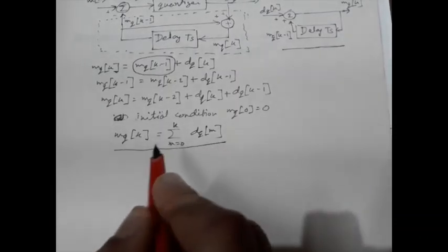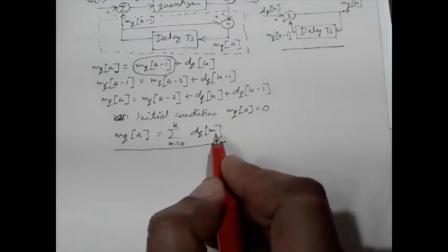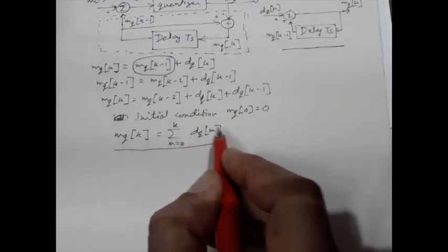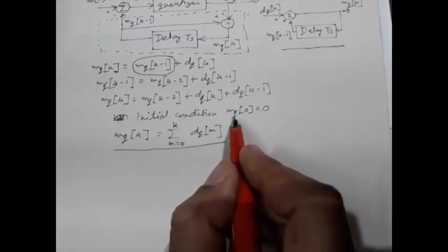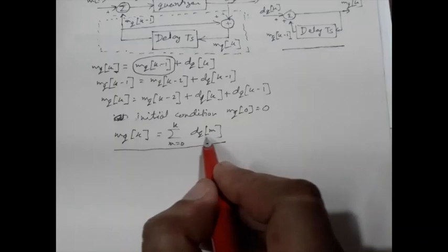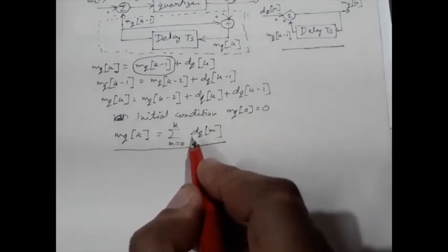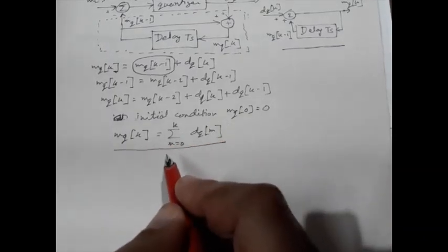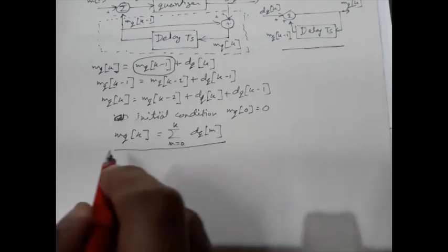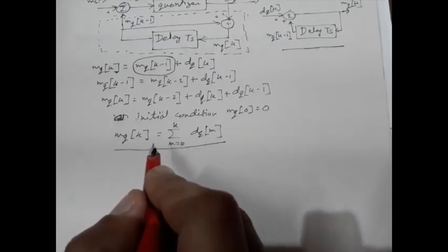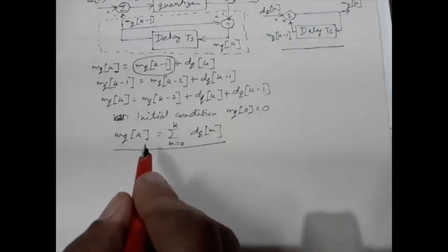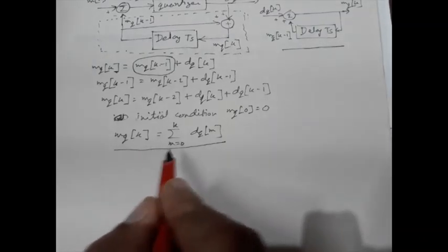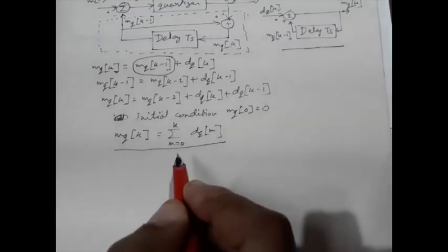and this is very interesting because at the right hand side, as you can see, there is no term associated with m. That means we are not transmitting the actual message at all. We are all the time transmitting the difference between the previous signal and the current sample. So the receiver of this one is nothing but an adder or accumulator.